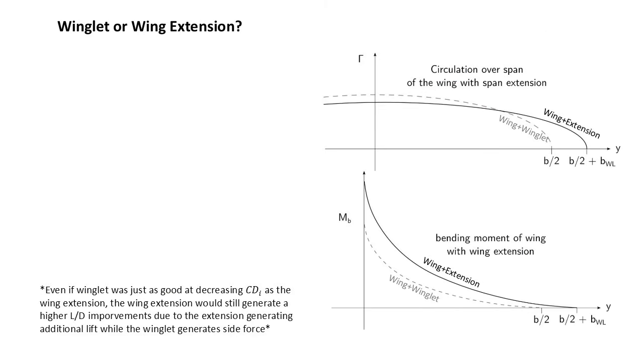Alright, let's say we're looking to increase efficiency for a conventional or tailed aircraft, and the addition of a winglet crosses our mind. Obviously, our first question to ourselves should be, do I even need a winglet to increase efficiency? Obviously, we're looking to increase efficiency, that's why the winglet would cross our mind in the first place, but can we do this with a span increase? Increasing the span, and therefore increasing the aspect ratio, will always be more efficient than that of an equal length winglet addition because of several reasons.